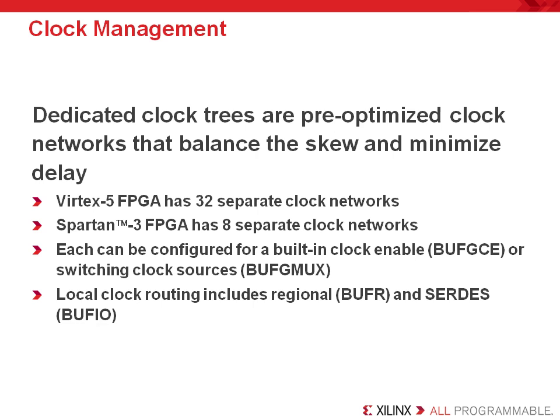These clock trees reference the BUFGCE, the BUFG clock enable, or the BUFGMUX primitives from the Xilinx Unified Library. The BUFG clock enable is designed to not only route a signal on the global, but allow a designer to actively turn the distributed clock signal off, like a clock enable, hence the name.